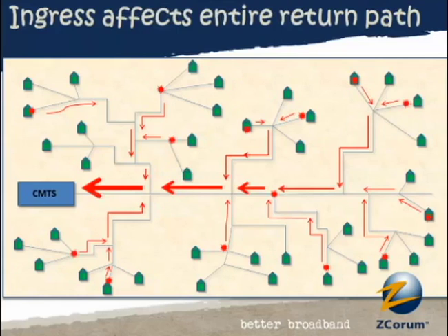We block it from going back downstream by using directional couplers in our taps and in other parts of our plant. So that noise can go upstream, but it can't really go back downstream in the upstream part of the frequencies. So we have all of this energy going up towards the CMTS, and it concentrates over that distance.